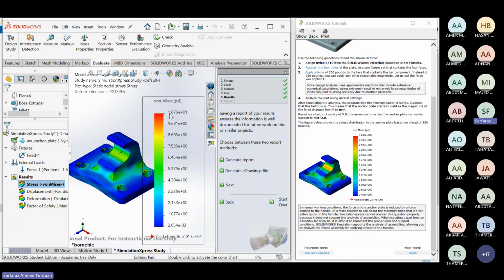As it gets below 1% or close to between 1 to 2%, the variation on the value that you're getting here is said to be accurate. So it's advisable to go with a finer mesh, but it would take more computing power and a longer time to get solved, especially if it's a complex problem. This is a simple part, but if it's complex, having a larger surface area, joints and so on, it would take longer.